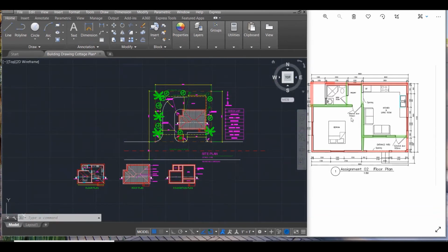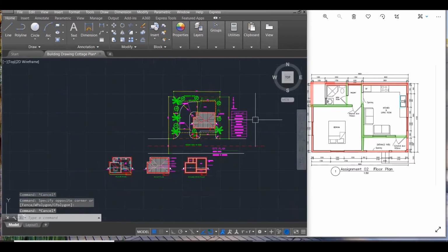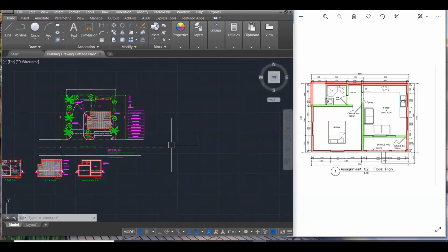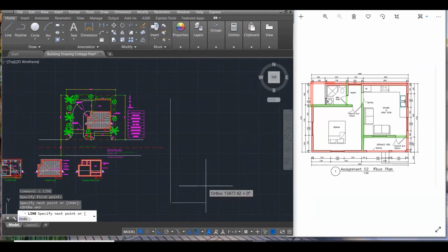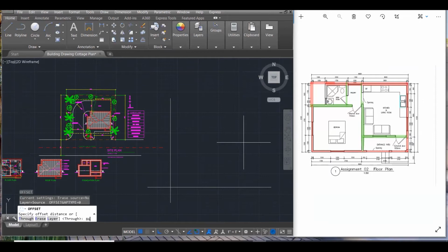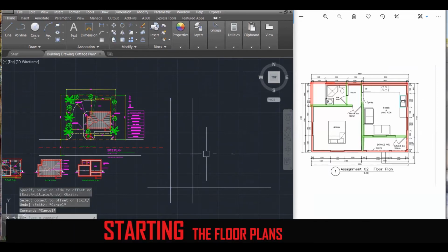So now that we understand how we're going to draw this, I'm going to start. Leave the joins there, leave all this in green and red, and then just start somewhere here. So let me find a clean spot and draw down a line so that I can start. I like starting like that. Why? Because I can offset in any direction and move very quickly. So the first direction I'm going to offset 8600 from the left to the right, and then offset up 6100.